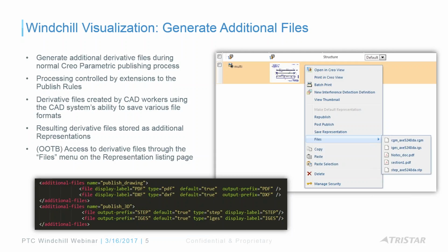Obviously if you have a good process, it will work. But what if that person's away for the day? It's reliant on people's knowledge and very manual processes. So Windchill introduced something called additional files that you can generate. Whenever a CAD user checks a drawing into Windchill, and this could come from Creo, or from other supported CAD systems like SolidWorks, CATIA, NX, Inventor, that plug into Windchill.